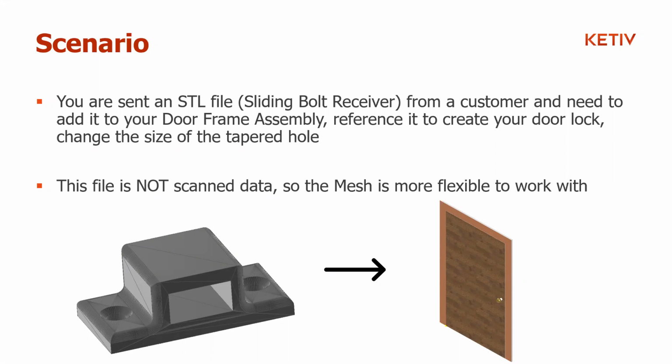And as you can see, there's a lot of complex geometry going on in that mesh right now. And this is before converting it over to a solid body. So again, just a reminder there, this is not scan data, so that's going to be more complicated to work with. But this is CAD converted data. And just a rule of thumb in general, if you're receiving a mesh, it's going to be a harder time than receiving a step file.